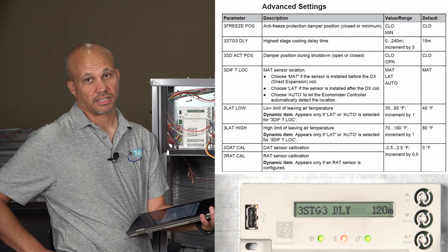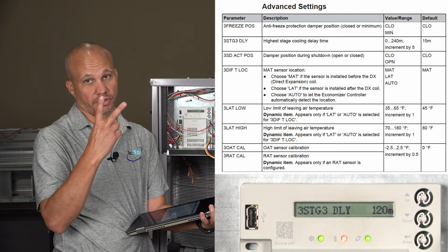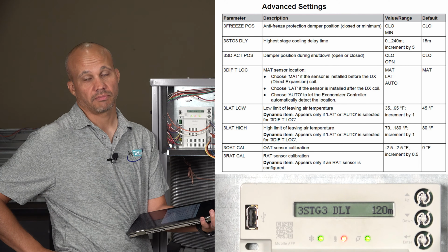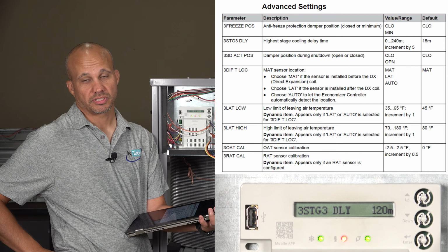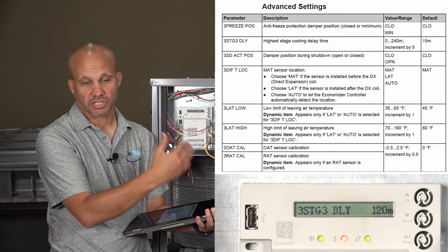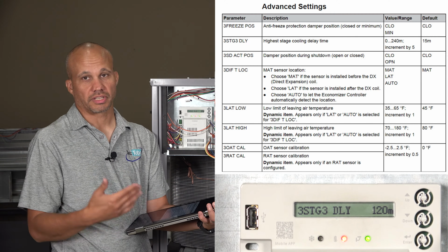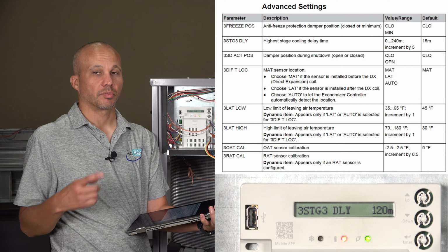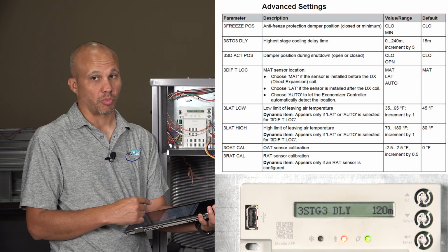I don't like that setting. I would increase that to 2 hours. I know that sounds like a very long time. It is, and it's long on purpose. The problem with 15 minutes, the default, is that within 15 minutes, it puts on that other compressor, cools the building down, everybody's happy, that sounds good. The problem is no one knows compressor number 1 broke.